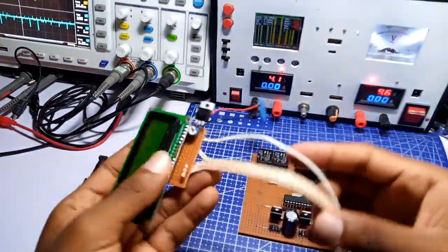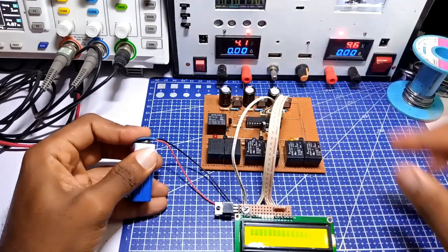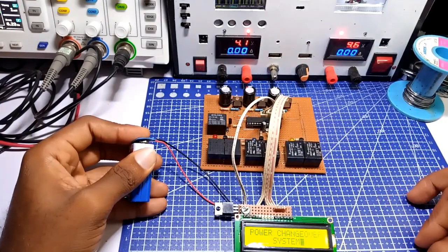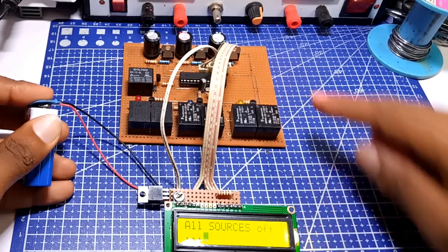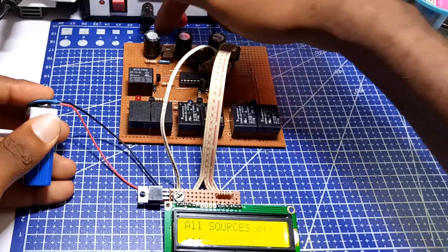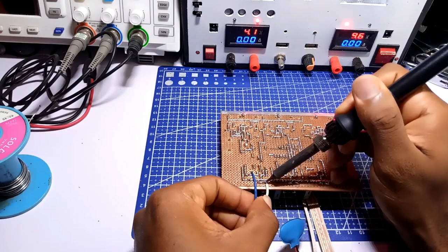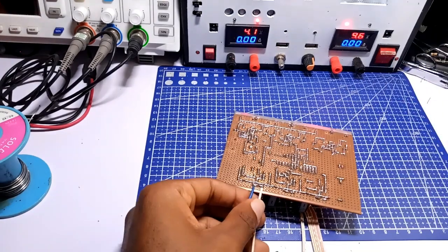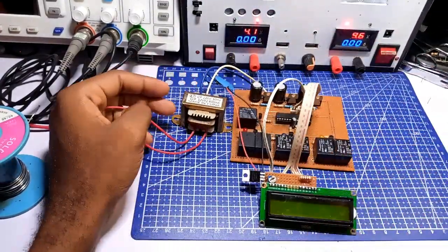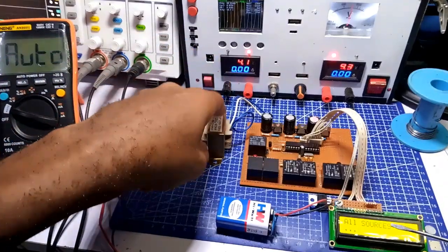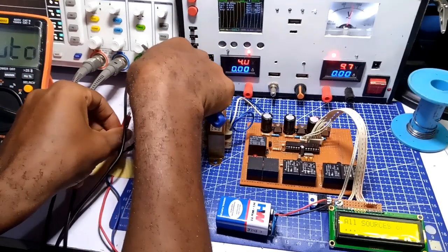Connecting the LCD and having it well in place, I powered the board using a 9V battery. Just as you can see, all sources are unavailable, and as such, that is the reason for the data showing on the screen. To power any of the sources, I soldered the secondary terminal of the transformer to the bridge diode. And this is for the primary source, which I'm going to be connecting to my grid line. I used an extendable wire to connect the transformer to the AC line, and once I powered the board, I got the power line detected by the microcontroller.